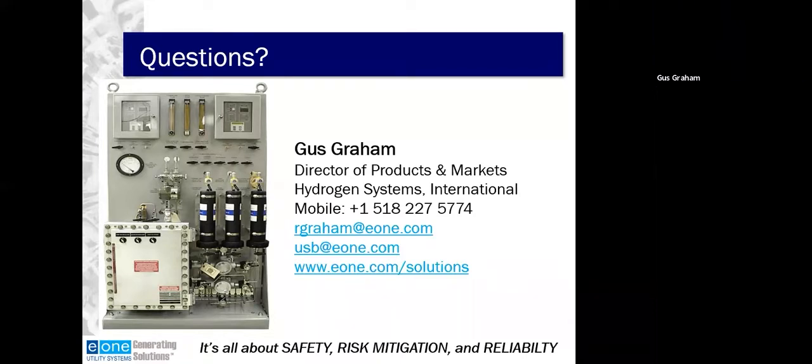So the purity compensation factor is fixed at the factory when we manufacture that cell, and that is an element that is put into the software when you replace the cell with a new cell. The purity compensation factor for the new cell would have to be entered into the software so that the mapping logic for the purity value is carried over for that specific cell. I hope that answered the question.